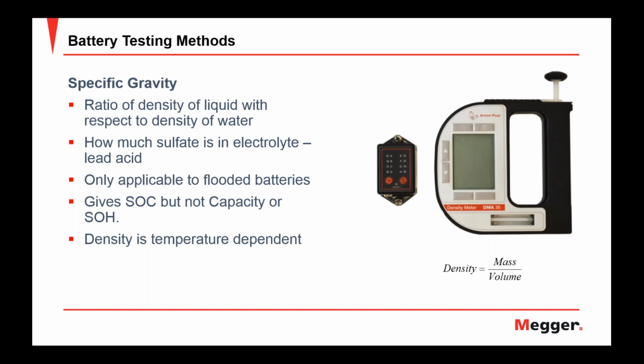If you have a NiCad battery, it doesn't tell you anything. If you have a lead acid battery, lead calcium, it's not going to tell you much. The only place this is really applicable is if you have a flooded lead antimony battery. In those cases, this will help you identify if there is antimony poisoning occurring. But other than this, as long as you're measuring the float current, this test will be sort of redundant.